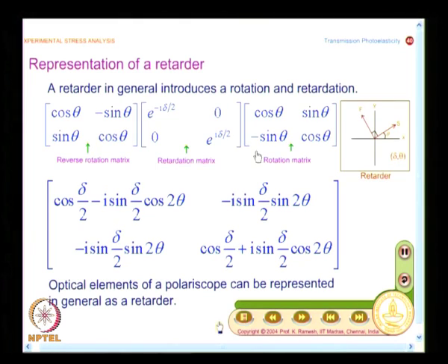So, you need to have thickness so that buckling is avoided. So, these are all practical considerations. You have to understand the practical considerations and also appreciate the approximations involved. And what we have seen in a retarder is, a retarder introduces a rotation, and within the retarder you are adding or subtracting retardation only along the fast and slow axis, that is only along the principal stress direction, remember this.